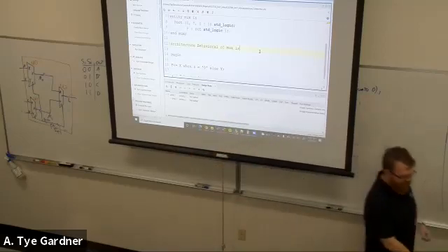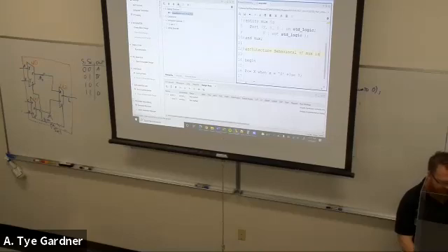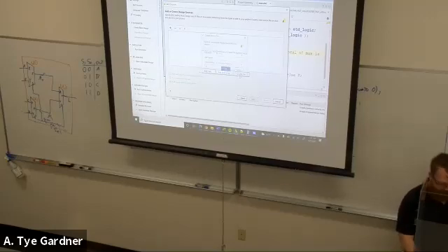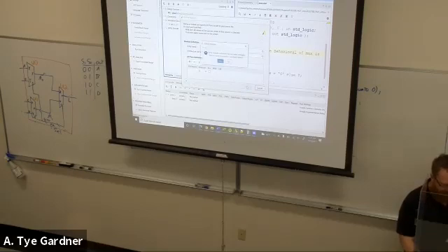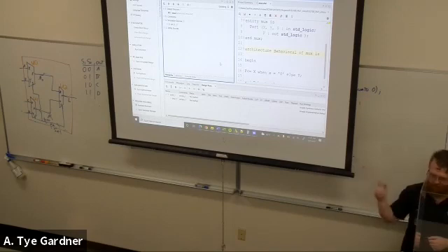Now, if I need a new component, I can pop open my sources window and hit that plus button again. I'm going to go ahead and create a new design source. I have to create a new file because I haven't built it yet. I'm going to call this one mux4, just like I did up on the board. Hit finish. It's going to suggest I make ports. I'm not going to do it that way because it actually takes longer than typing them out like I showed you there. It actually takes longer to use that window.